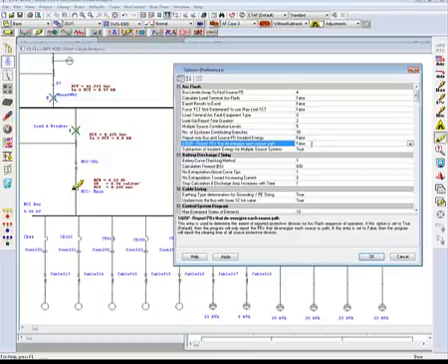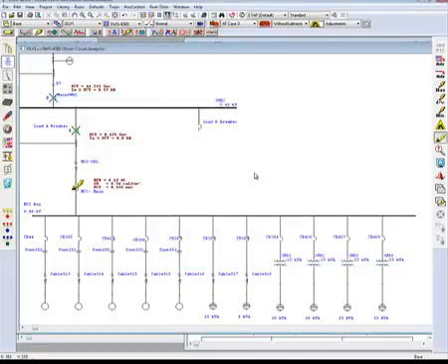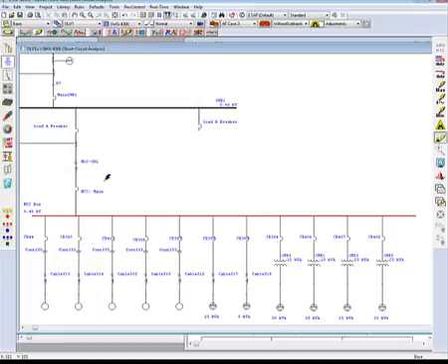If I were to set this to true, you will only see one operation because you're only telling the program to display the first device to de-energize, completely de-energize your fault. Now notice that the upstream devices are no longer flashing. And we could go ahead and show this with the other system with multiple source contributions.